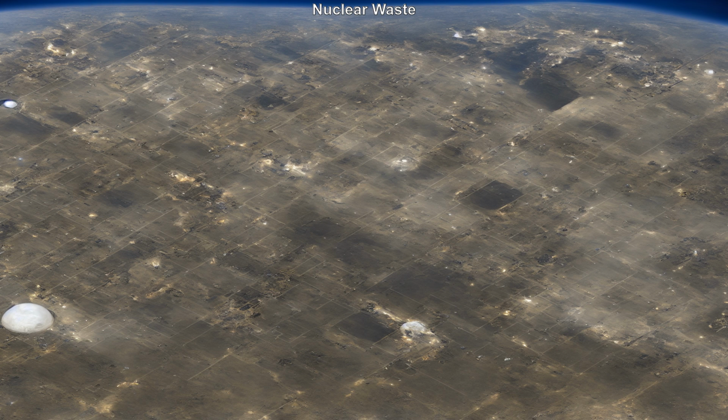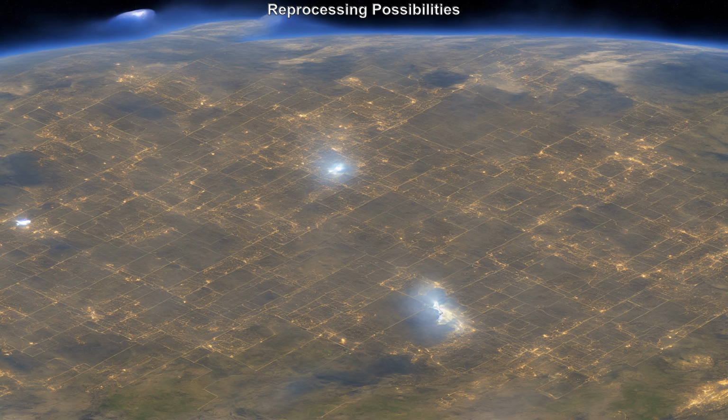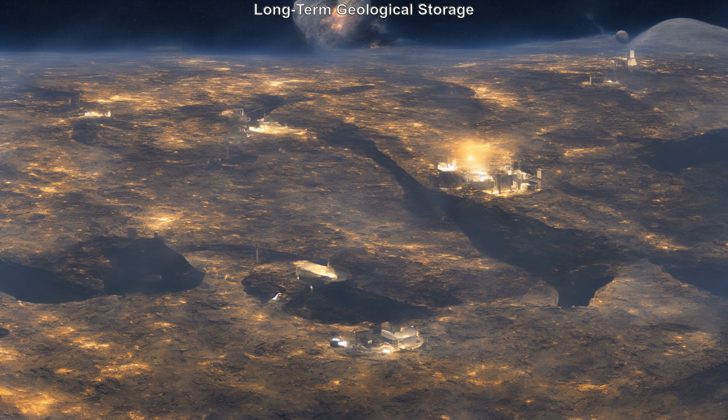Nuclear fission produces radioactive waste, which requires careful handling and storage due to its long half-life. Spent fuel is initially stored in cooling pools to dissipate heat before being moved to dry cask storage for longer-term management. Reprocessing can extract usable uranium and plutonium from spent fuel, reducing the volume of waste and potentially generating more energy. The most widely accepted long-term solution is deep geological storage in stable rock formations to isolate the waste for thousands of years.